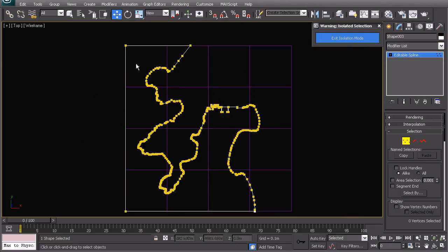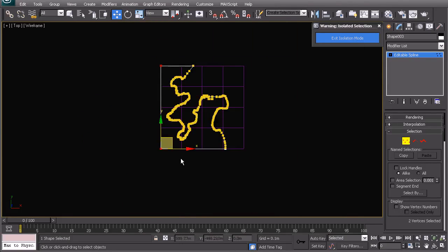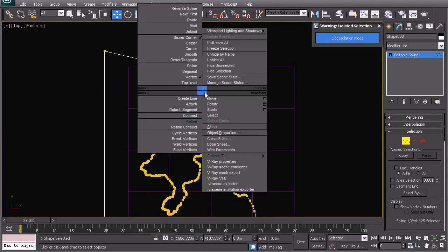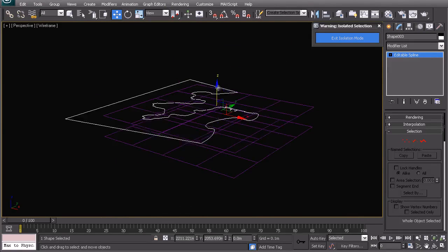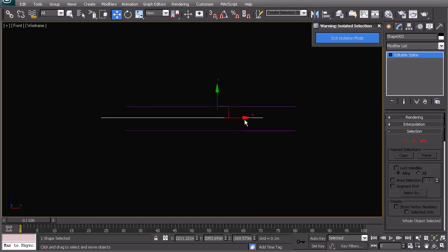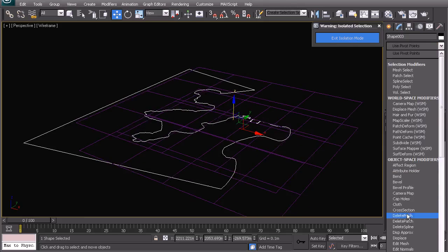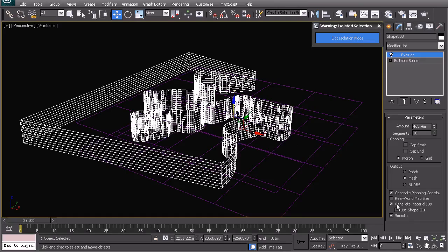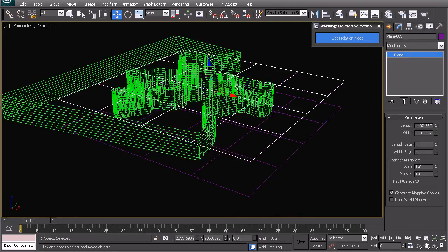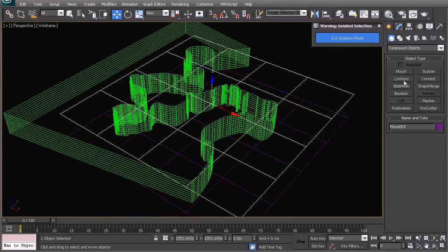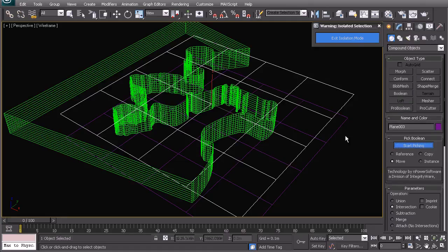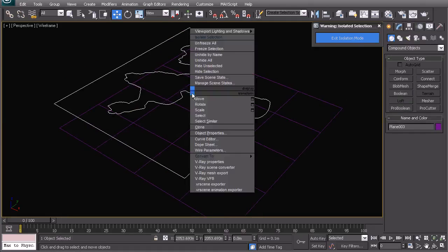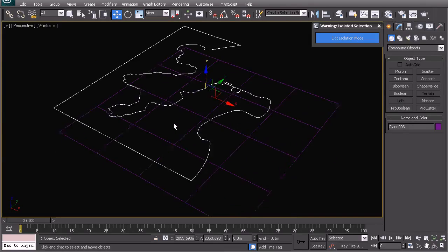So we can do the same thing with that. We can move these out. This one slightly up, this one slightly down, just to make sure that everything is in the correct place. And the same process here. We move this slightly down, slightly below. That's correct. We're going to extrude this, EXT, and same process again, except this time we're going to choose intersection. And we pick that. So now we're left with the ocean.